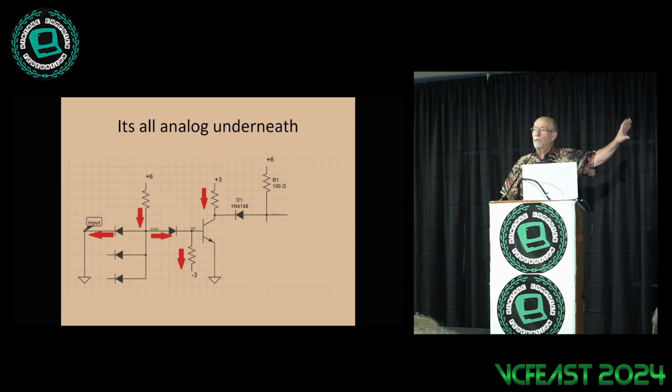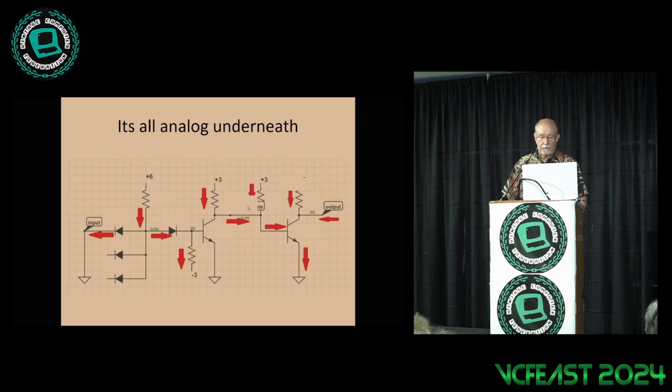And if it had been a normal gate on the other side, the second inverter, that would have been what we would see, because the diode would have nicely isolated things. But to save on the cost of the diodes, IBM wired the second gate just directly to the transistor, no diode. So the +3 volts is actually flowing down through the last transistor, pulling that down to 0.9 volts. That's why you see this anomalous looking result. You have to look at the actual implementation sometimes to figure out what's going on.